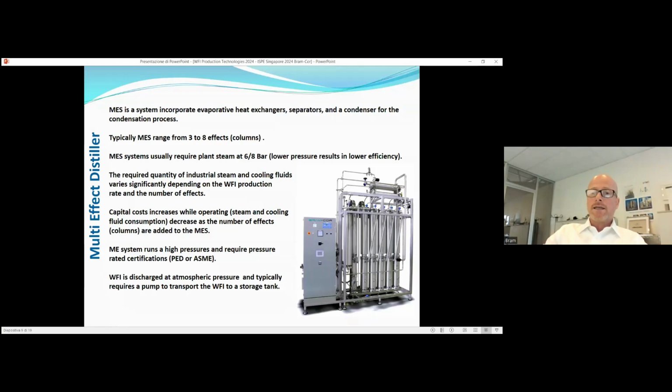The capital cost increases, while during operation, as I was saying, steam and cooling fluid consumption decreases as the number of effects is added to the multiple effect. The more columns you have, the less consumption of utilities you have.